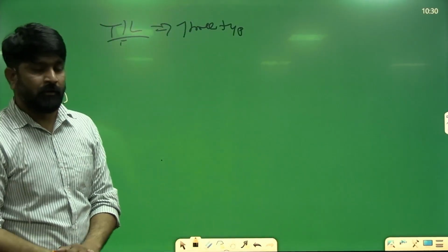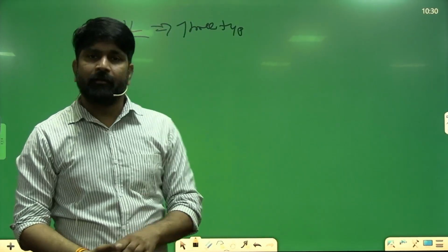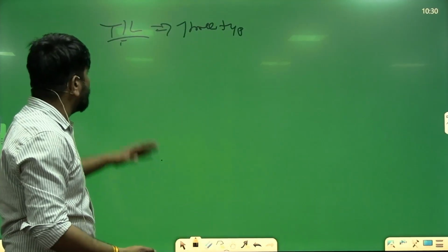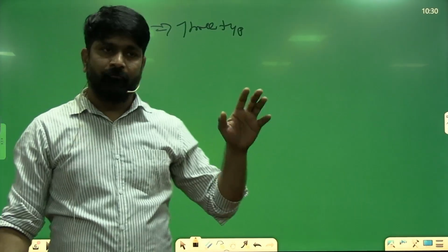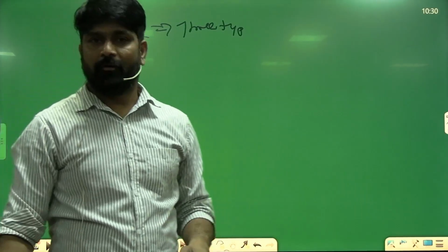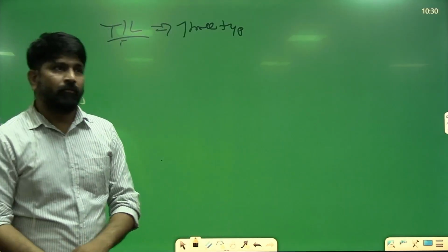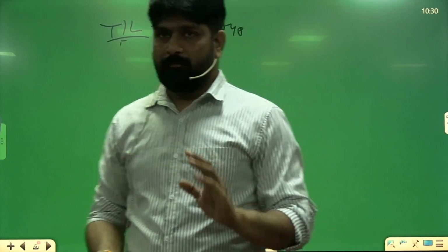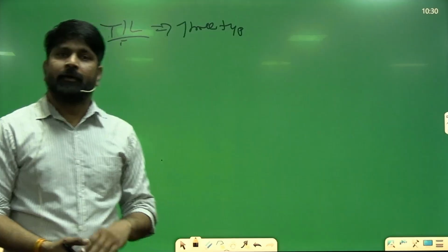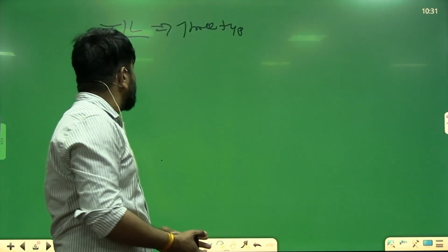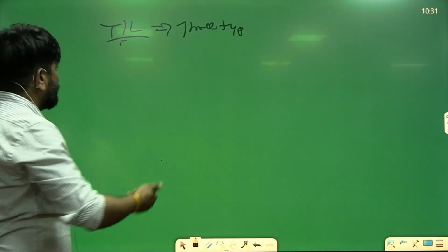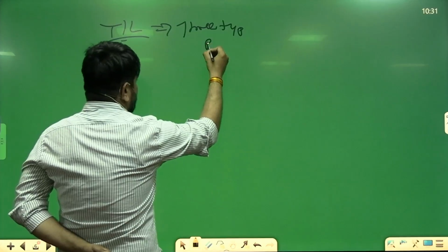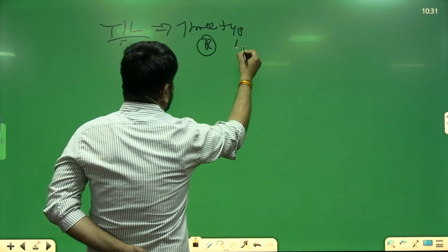In the small transmission line, the voltage rating will be less than 20 kV, and the length will be less than 50 kilometers. For the calculation of voltage regulation and efficiency of a short transmission line, we consider resistance and inductance.